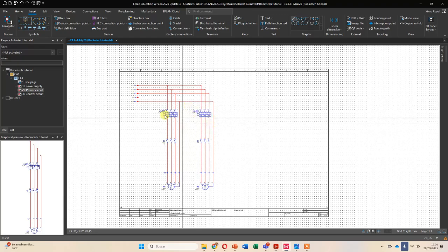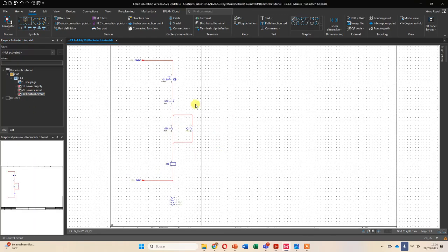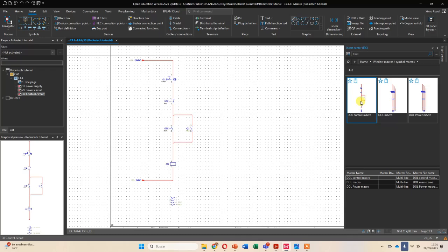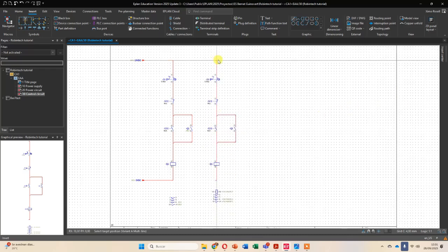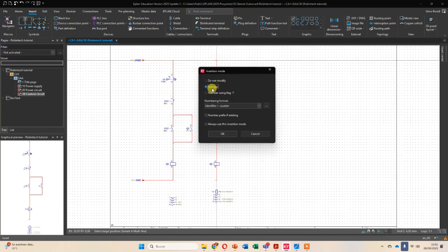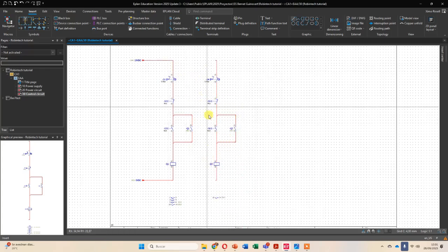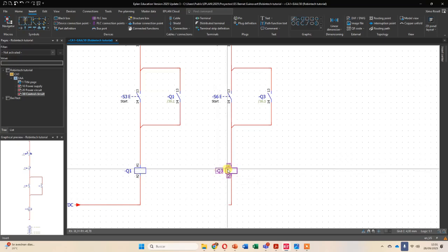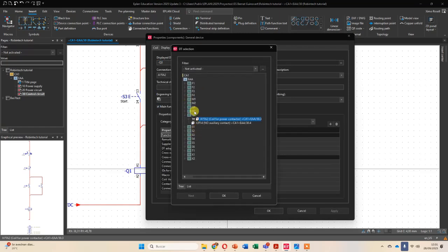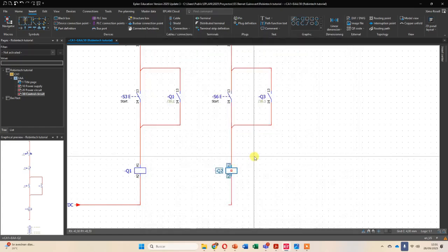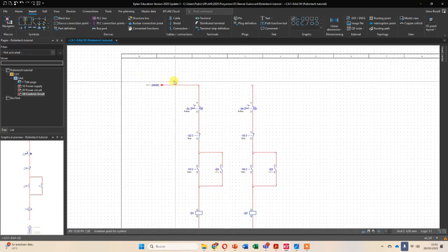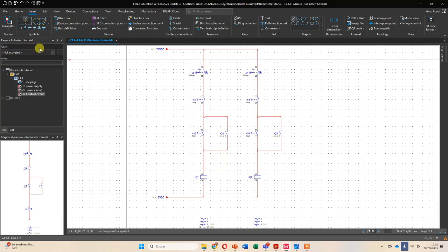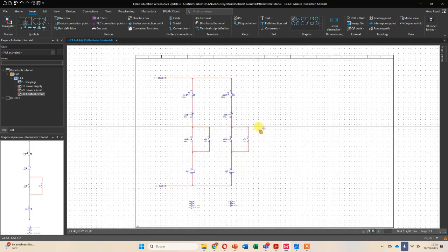Okay, the same can be done in the control circuit. Okay, so in here we will go to Insert Center, DOL control macro, we drag, and then we place. Okay, again we will usually choose number, and again we have to be very careful with the labels and the DT, with the device tag that we have. In this case, this Q3 most likely will be Q2, so it's labeled, so it's linked to the one we have just inserted. Okay, now we would complete the circuit, not this one, but this one. Okay, and with that we will have the electrical schematics of the control of two motors.